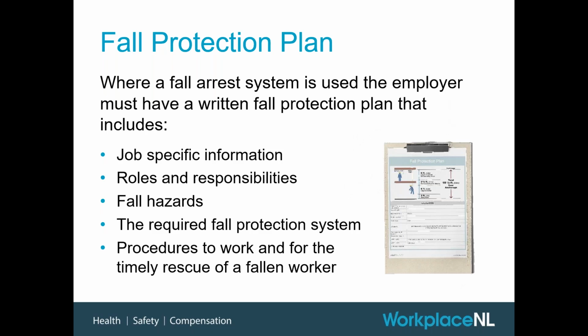Wherever you use a fall arrest system, again, you need to have a fall protection plan. And what you need in this plan is a little bit more thorough than what you would need for a restraint system. In addition to basic job information, roles and responsibilities, hazards, as well as whatever equipment you're going to use, so the system itself, you also need to have a plan in place to rescue someone if they fall and are in their arrest system and they're suspended.